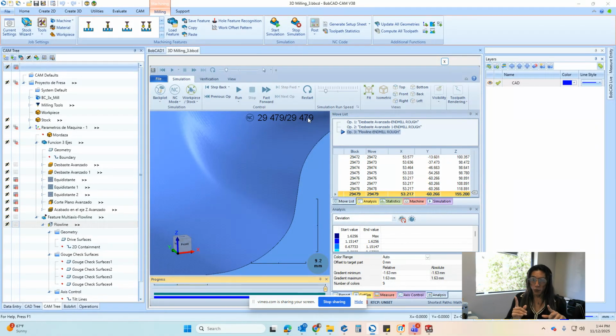Now, there's a warning with this. You have to be more conscious about your surfaces. If there's an opening on your surface, if there's an area that is broken, the toolpath will go in there. Sometimes the mesh toolpaths will just clean that up and follow the surface. With premium, it will follow the surface. And also you need to be conscious of the normals of your surfaces.